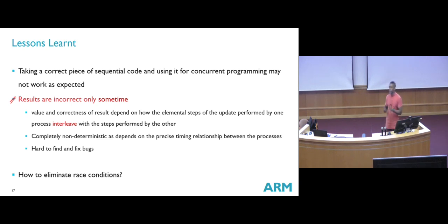The one that causes the most headache is the one that happens once in a while. If it happens once in a while, it's very difficult to troubleshoot because you do not know where to start. If it happens consistently, if every time I press this button the system crashes, you know that something is related there. I can troubleshoot maybe the button hardware, the ISR, something. So there is a point of entry where I can start to troubleshoot.